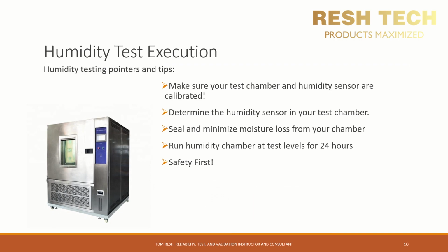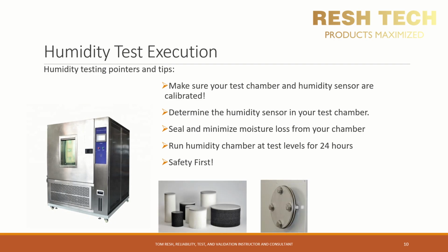You also need to make sure that your chamber is sealed as best as you can get it. Make sure to have port plugs installed so you slow down the loss of moisture from inside of your chamber into your test lab space. Even better, if you aren't going to run cables through your port plugs, install a cover with a gasket to really get a good seal.